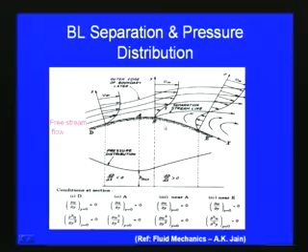With respect to this figure, we have analyzed the flow over a curved surface and how the velocity changes with the boundary layer separation, from the start to after the separation takes place. Initially, with respect to the boundary layer, the velocity pattern is different. Where the boundary layer separation starts, the velocity behavior is different at that section. After the separation, there is a reversal of the flow direction, a change in direction of the velocity, and that is why we say a wake is formed.